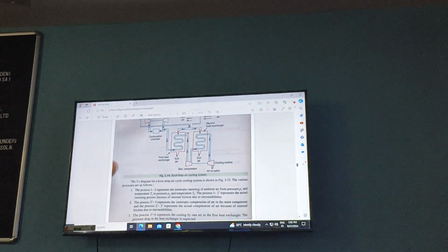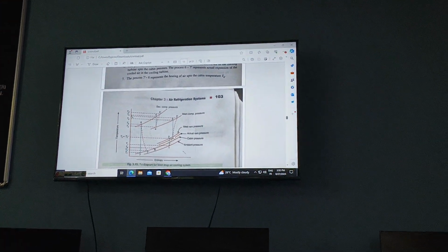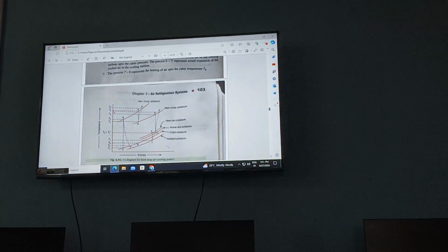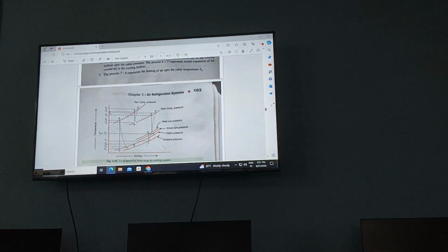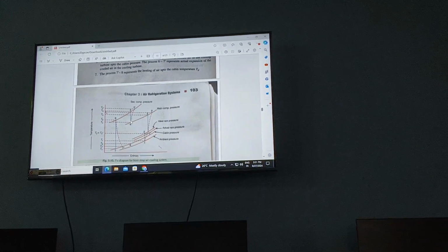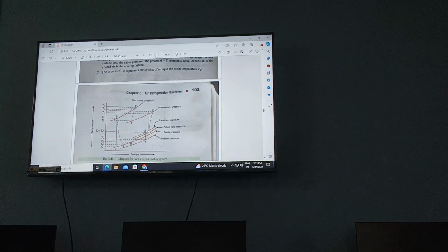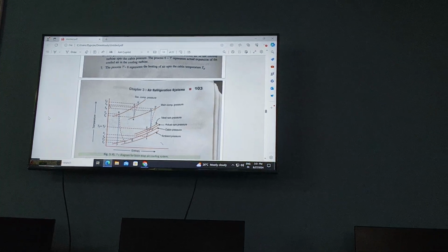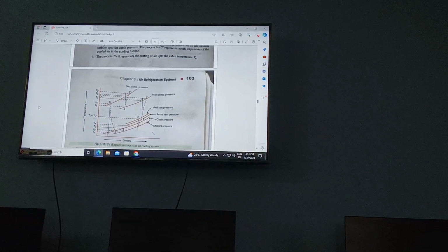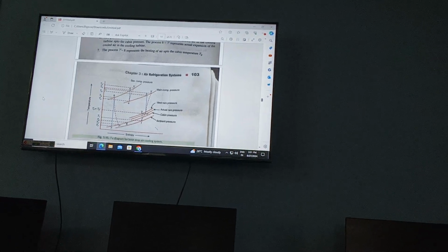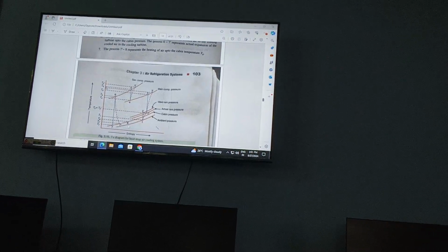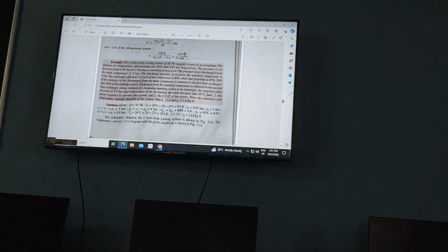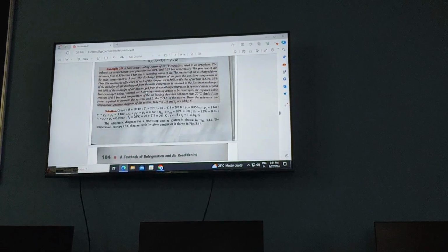Now processes are there. 1 to 2 ramming, here the TS diagram. 1 to 2 ramming, 2 to 3 isentropic compression, actual, all these. Okay. Now here 2 compressors are there, right? But while calculating the power consumed by the compressor, we need to calculate the power consumed by the main compressor only, not the secondary compressor. Why? Because the secondary compressor is run by the turbine only. So there is no separate power we are providing for this, right? Similar things are here, right? All these are the constant pressure lines. Okay, these formulas. This one numerical is there on the bootstrap.